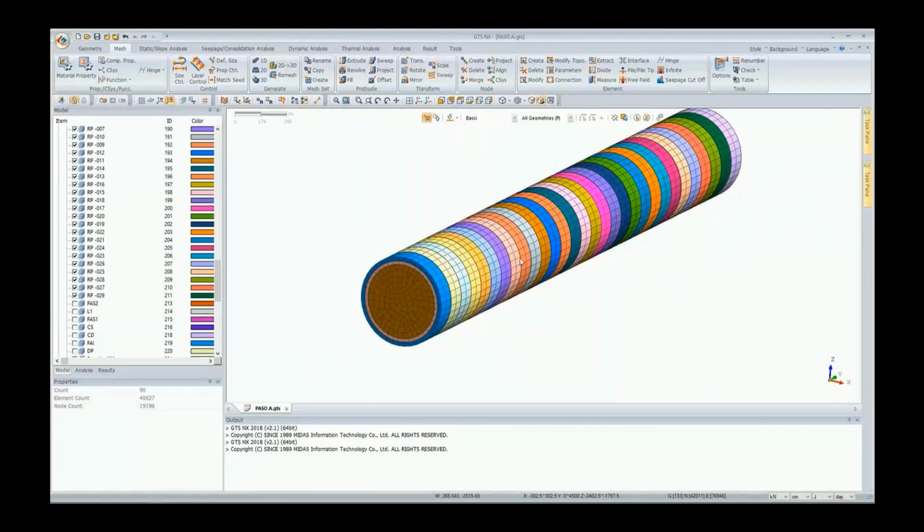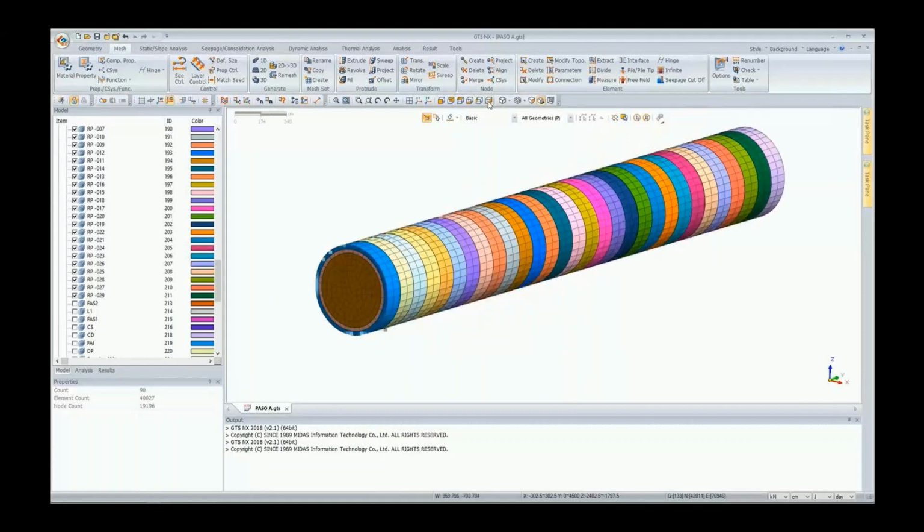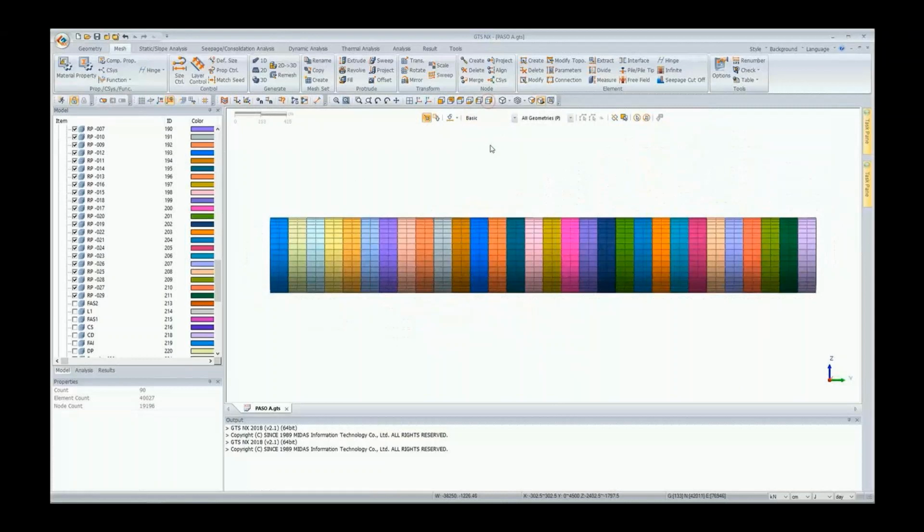And so we see that these sets are going to be activated in a sequence. We're going to simulate the advancement of the TBM every 3 meters, so we're going to do every other set as simulating where the load is going to be applied. I'm going to do my side view and modify the selection filter to intersect. And I'm going to draw these series of diagrams to deactivate alternating sets, basically leaving one on and one off to simulate the advancement of 3 meters each.